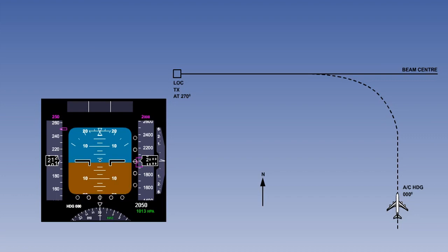If we look at an aeroplane that is intercepting a desired navigational track using only raw data, we will see that the aeroplane fails to anticipate approaching the track. So the aeroplane flies through the track and then has to continue the turn to intercept the desired track from